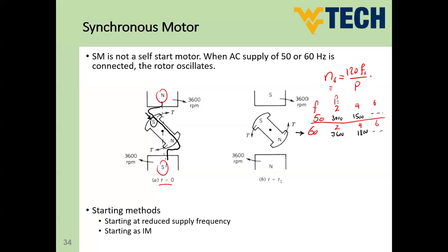For instance, if you boil some water to 100 degrees Celsius and disconnect the source of heat, it will take a very long time until the water turns cold or returns to regular room temperature. So the thermal time constant is much larger than the mechanical and also much larger than the electrical time constant.